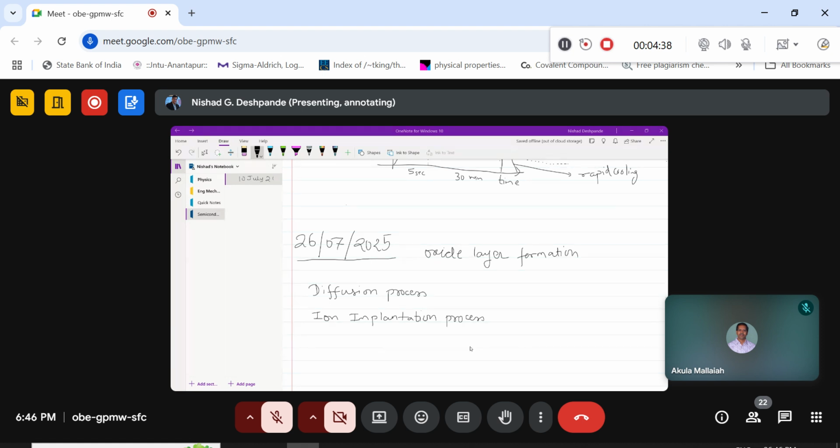This is the process which we call the induction process, the diffusion limited process. So these are the two different processes when you try to have the oxidation on the silicon surface. That we have discussed. This is how the wet and dry oxidation processes occur, and one can say that there are linear or parabolic growths with respect to time for different wet or dry oxidation processes.